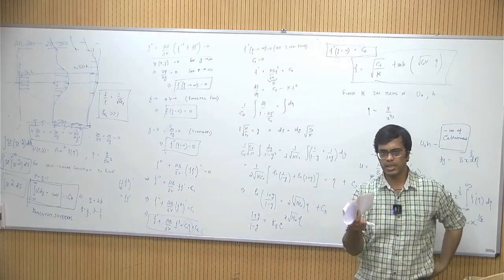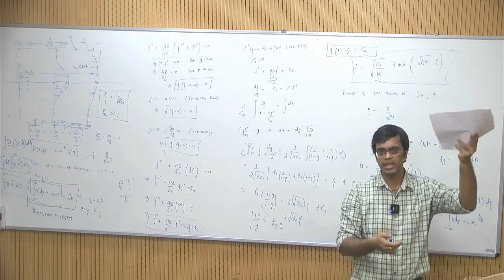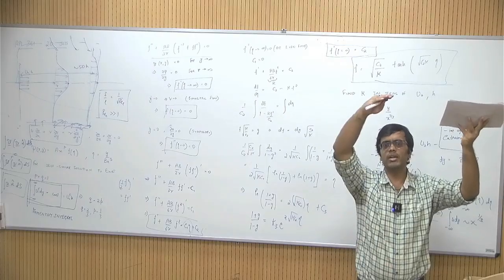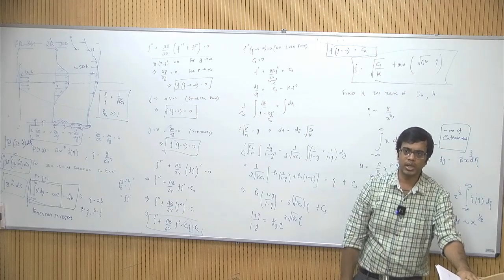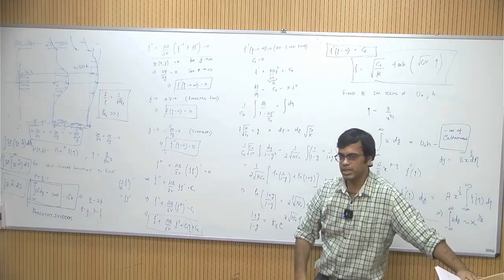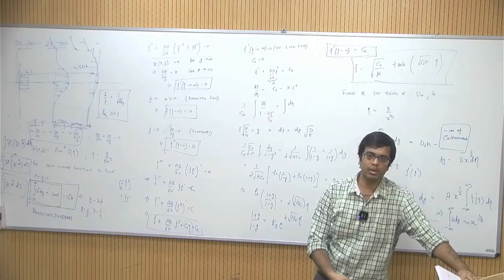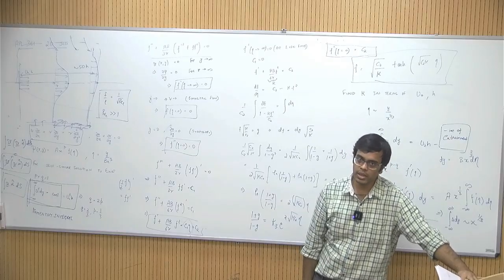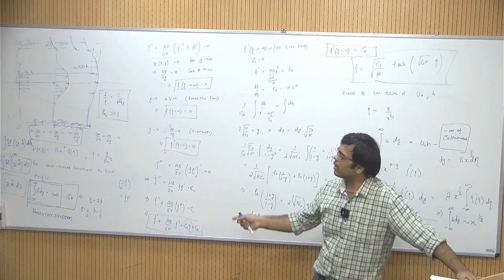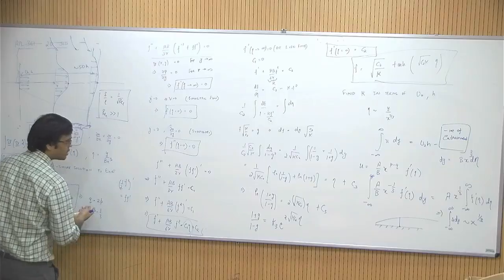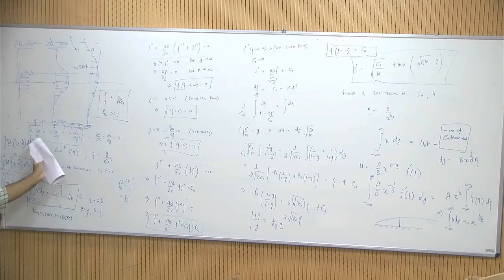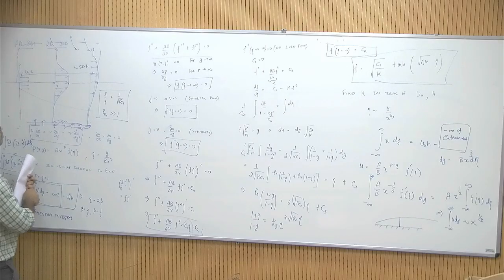In that jet, you take the measurements up to 50 centimeters from the jet orifice, right? If you take it further away, around 50 centimeters to 1 meter, you will see self similarity, although that will be a turbulent jet, so things are very different here. But if you can get a laminar jet, you will see self similarity. You can think of these as academic solutions because they exemplify the power of self similarity and how to use your Navier-Stokes equations in approximations. And the approximation that we have been discussing is this.